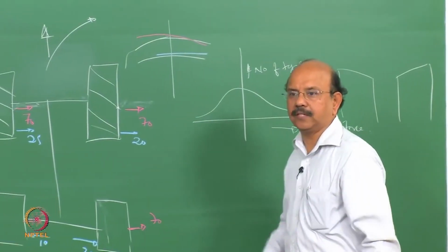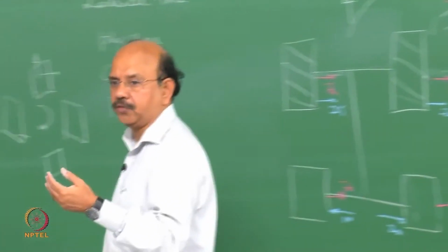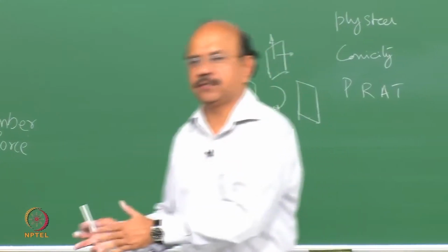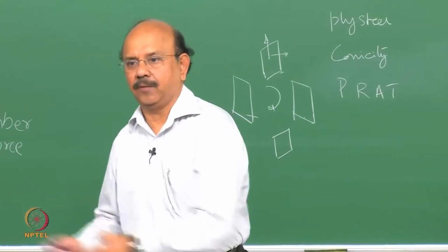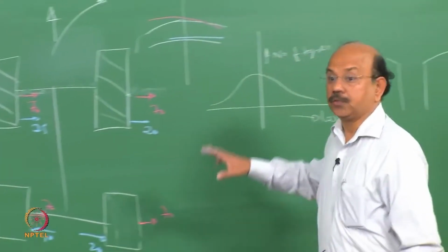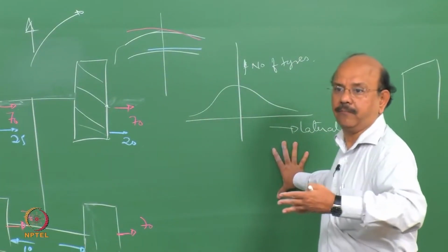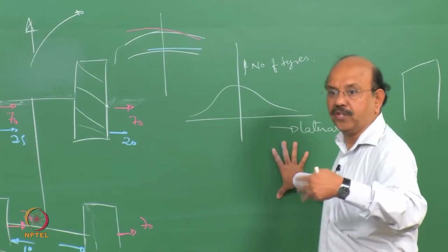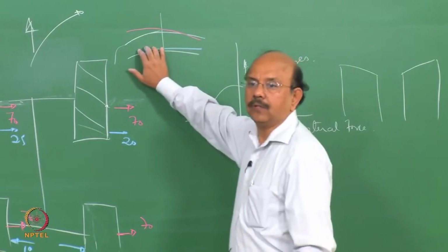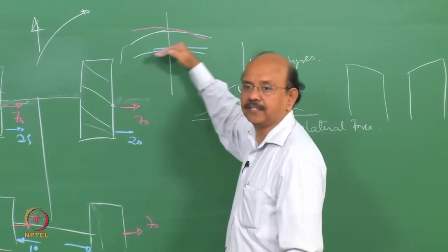In a pre-cured state, when the curing has not yet taken place, it becomes highly viscoelastic. In other words, it starts flowing in a very short time. So due to so many reasons, these belts are not necessarily symmetric. So this belt gets offset.